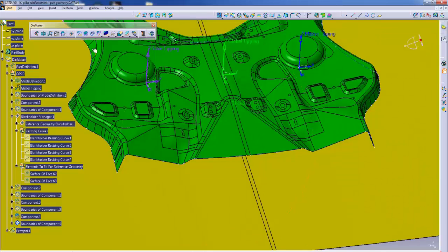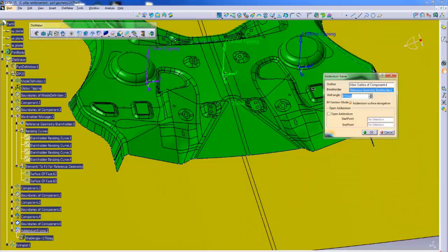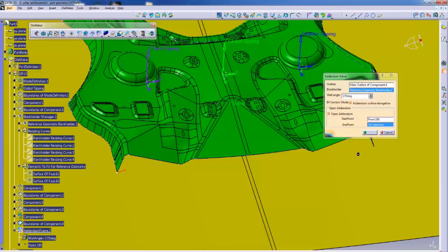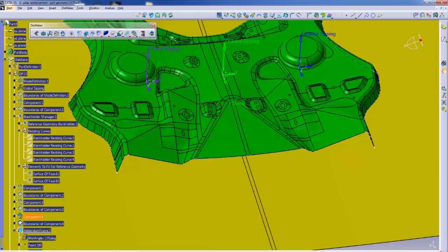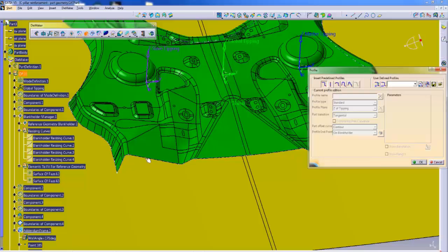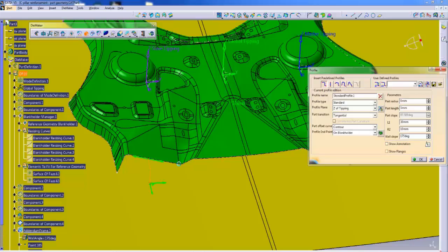For building the addendum surface, the user can use specific addendum functionality, but is also free to use any of the part preparation functionalities. The first step is to define what kind of addendum will be created: outer addendum, inner addendum, part on binder, or multiple punches.